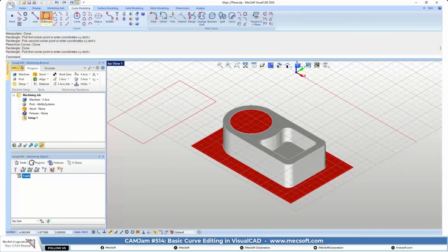And as you see here, the command remained highlighted. There's an option up here called toggle continuous command recall. If you have that off, the command will only work once, okay? And then it'll turn off. If you have this on, you can use it multiple times. Okay, so basically I was just going to get you to do some basic trimming and calculating.